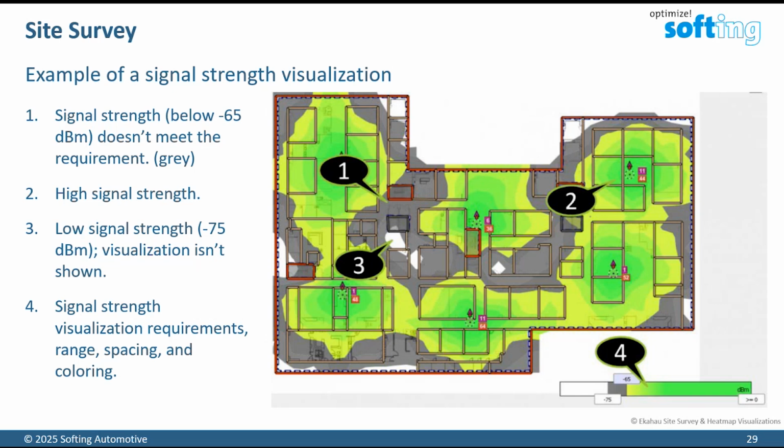Then you have boundary or standard values that you should consider, and that is with this slider, labeled with 4. The slider allows you to set to which dBm value you want the signal strength to be good, and when it should start being bad. You should consider the following boundary values. For data transmission, the boundary value is typically -72 dBm.